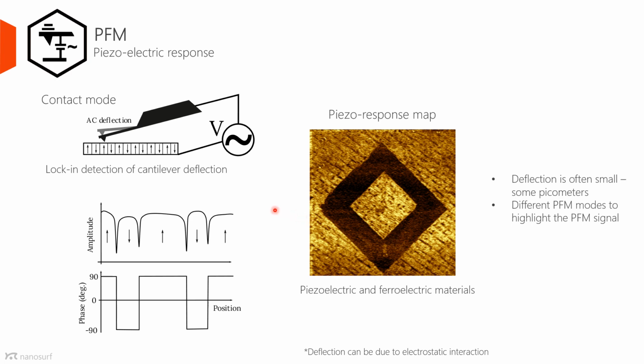Piezoelectric force microscopy, or PFM, is measuring the piezoelectric response of the sample to the applied voltage between the tip and the sample. This response is usually very small, of the order of some picometers, and it would be very difficult to measure it in a DC deflection mode. That is why in such a measurement, while the tip is scanned in contact with the sample, an AC voltage is applied at a certain frequency, and the tip deflection is also measured at the same frequency with a lock-in